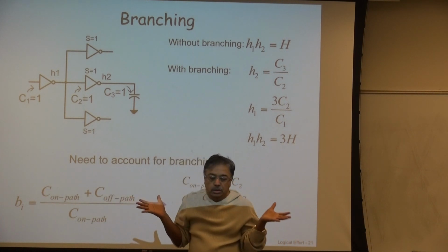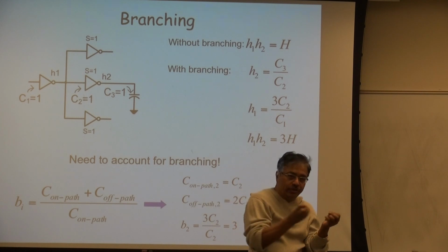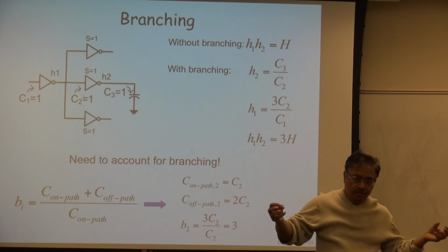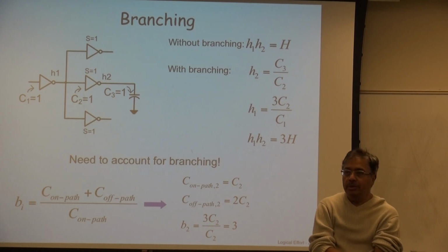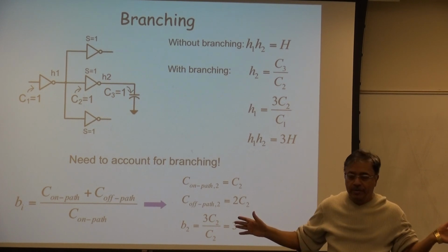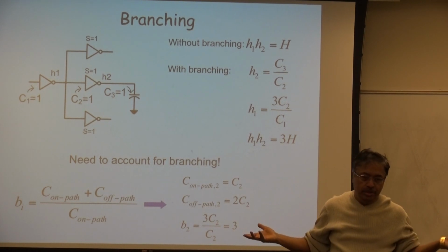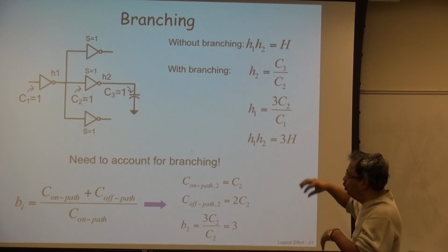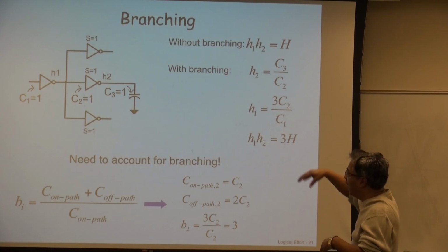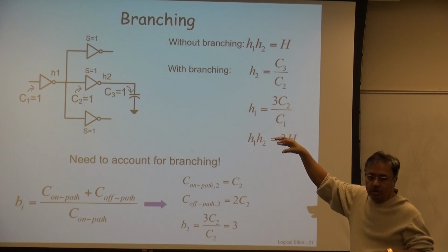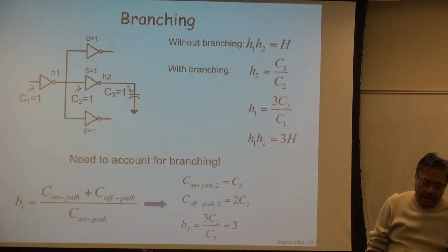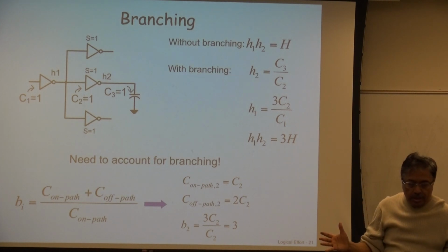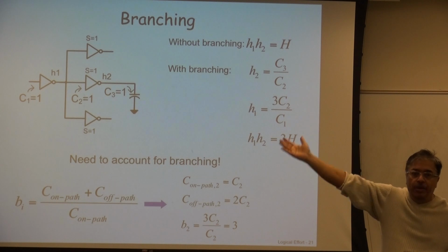I mean, you can use some CAD tools to extract out the capacitance and find out. But when you are starting from scratch, you don't have any simulator or anything, then you just assume the sizes of the input capacitances of those paths. Because, okay, what happens is that in a large design, you cannot optimize every path in the world.